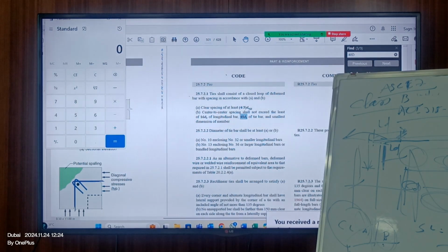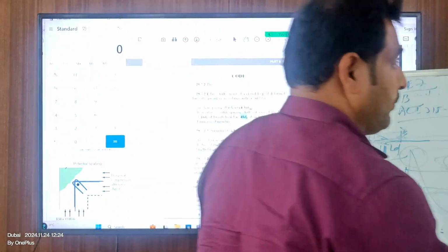Where it is not going to be applicable is also there because you do have 3 equations. Straight LD, if you want to still provide the hook, that is 12 times of diameters which you are going to provide. Like foundation, I am going to take it LD, whatever you say is 300 millimeters or 250 millimeters, right? If I do a massive raft, then I only go for LD. But separate equation if I go for the hook, which I am going to calculate additional to this length actually. I'll show you another thing.